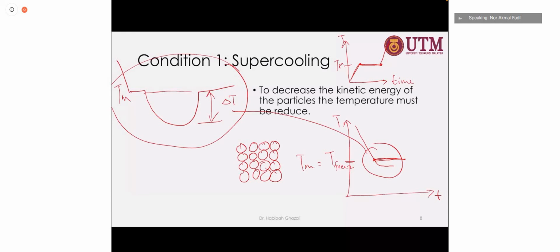So it starts to grow during this point, and it stops at this point and the temperature increases, because of the heat released during solidification. That is the reason the temperature rises. This is the maximum reduction of temperature, the maximum supercooling temperature, which allows the formation of a nucleus. At this point it has formed enough atoms, and then it starts to form a nucleus.